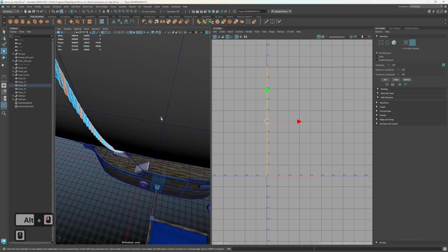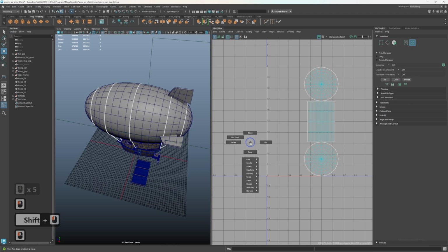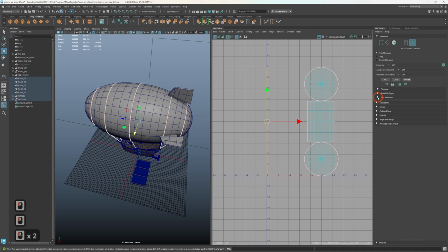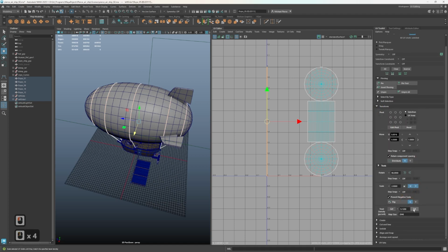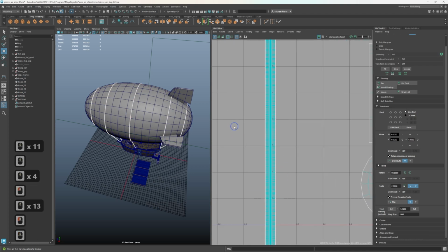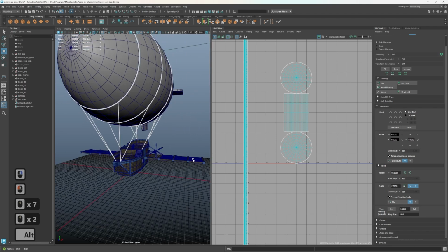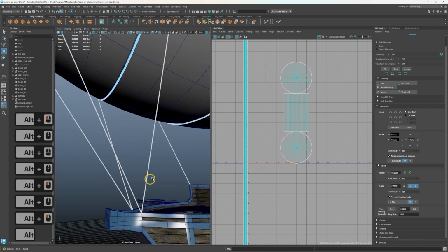Now, you could make them a little more accurate, right? So if I were to grab, obviously, these guys, I would select all these guys, UV shells, select them, right? Now, this might be a little much for the computer, so be careful about doing them all at once. And then I would go to the transform, and I'm just going to make sure I set them to the same texel density as everything else. And you'll notice now I've got larger ropes, but they are resembling their actual size. It's perfectly fine that they're overlapping because you'll be using a tiling texture that would represent the rope itself.